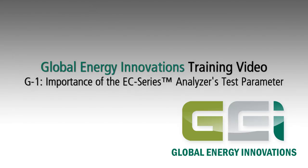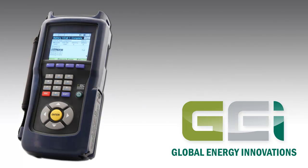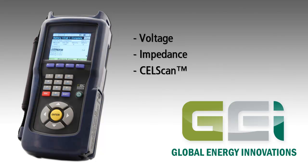This video reviews the different test parameters measured by the EC series analyzers and reported in IBMS. The EC series analyzer measures three test parameters: voltage, impedance, and Global Energy Innovations' parameter, cell scan, which assesses the chemical properties of the batteries.